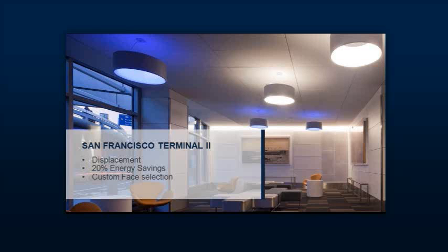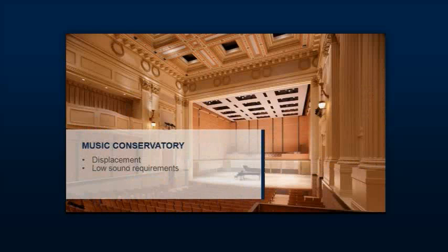So the first building in this presentation is CalISO headquarters in Sacramento. It's a platinum building. They used underfloor air distribution for the bulk of the building, and in select areas, displacement incorporated in the walls, in conference rooms and other spaces. What they achieved was a 40% more efficient design than what Title 24 called for. And they also achieved individual control of the diffuser volume by fan operation on this unit.